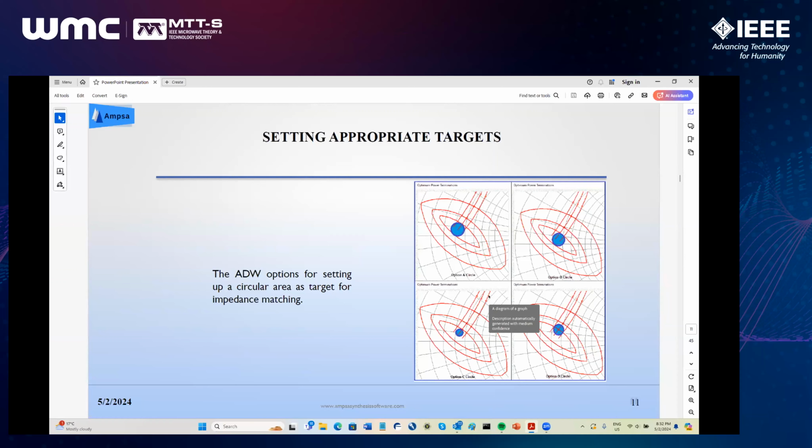Now, also in continuous modes, you cannot have just arbitrary reactance added to the resistance for the original mode. You limit it. You can only add so much reactance. So this is the same concept. You can add so much reactance to say I have so much Q. So basically, you accept this Q and you accept this Q, and then all of inside this area will be good for efficiency and power. So this is what this is telling you. So if I then choose which circle I want, I can basically target a circular area which will have reasonable power and efficiency. So that's the basic idea.